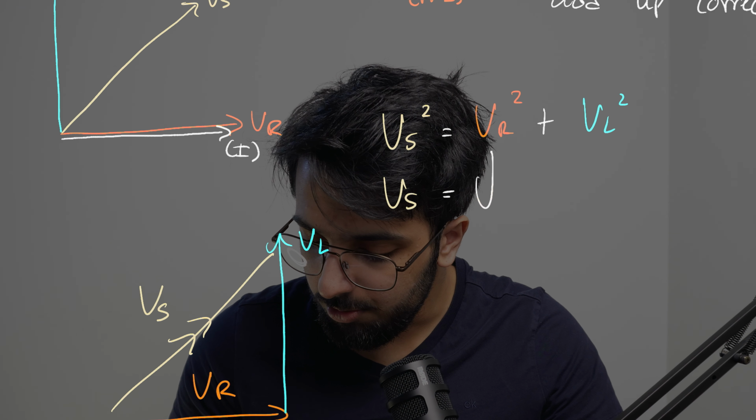And because we know the voltage across our inductor is equal to the current multiplied by the reactance of the inductor, if the reactance of the inductor increases, therefore the voltage across the inductor is also going to increase. Okay, and because our supply voltage has not changed, therefore, because the voltage across our inductor has increased, the voltage across our resistor must decrease, okay?